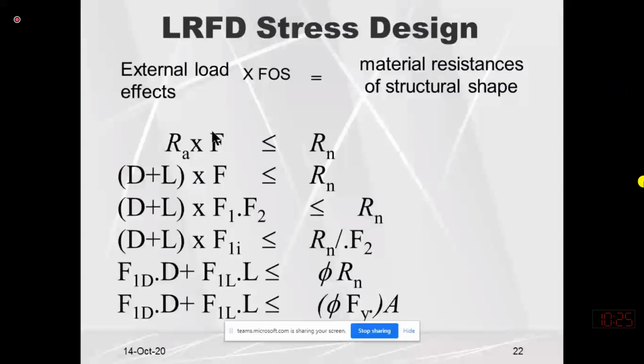I have also explained that applied load effect may be of different types. Applied load means the internal force which is acting in any structural member. That may be compressive force, tensile force, bending moment or shear force. Similarly, with reference to the applied load effect, the capacity would also be different. For bending moment, capacity will be the bending capacity. For tensile force, capacity will be tensile capacity, which is the combination of geometric resistance and material properties.